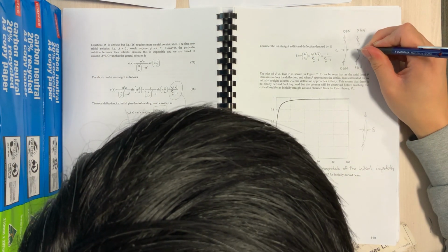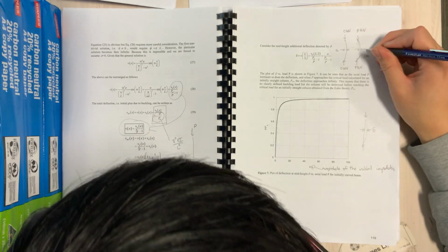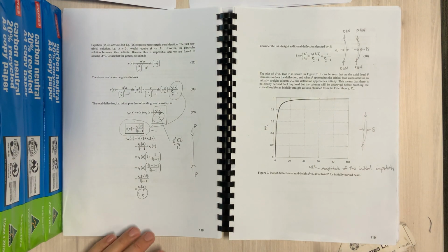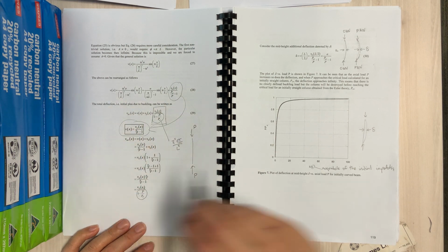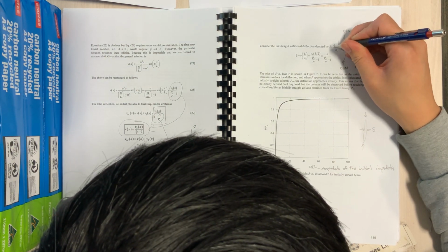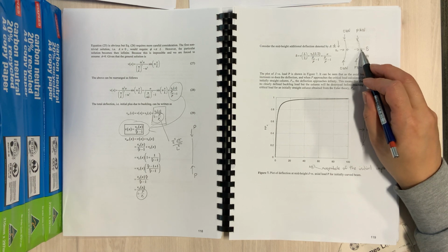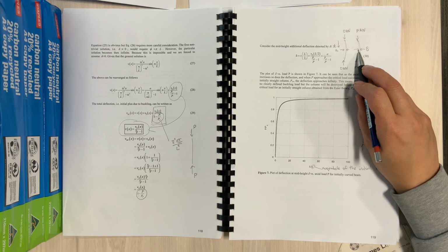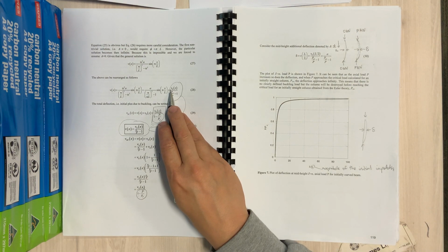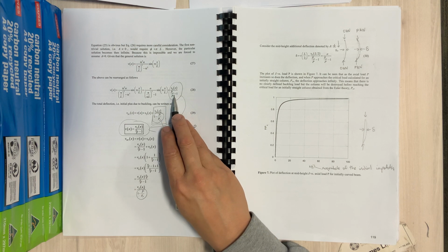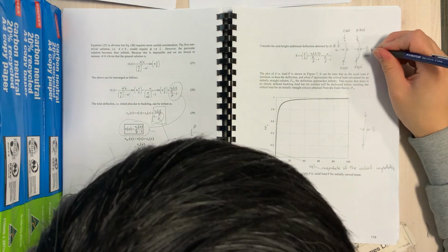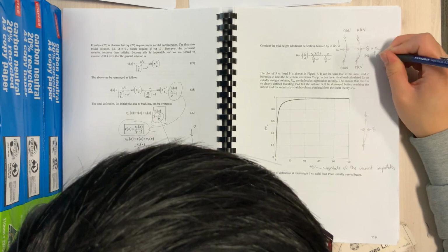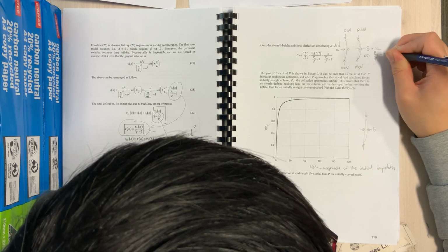So now at mid-height, we're talking about that deflection there, delta. That would be the mid-height deflection, not the total deflection. And here we can see the mid-height deflection delta when x is L over 2. So that's your x-axis. And when x is L over 2, which is the halfway height, then that additional deflection is going to be equal to the magnitude of the initial imperfection, because that would be your V0 at L over 2, PCR over P minus 1. So we'll say that that is equal to A divided by PCR over P minus 1.